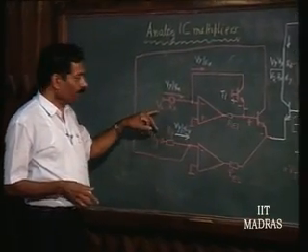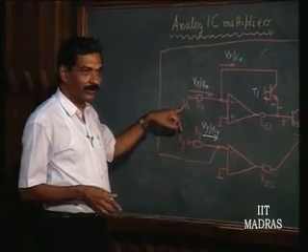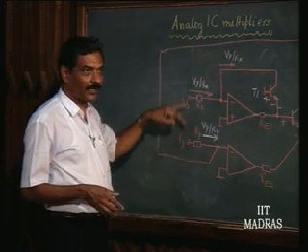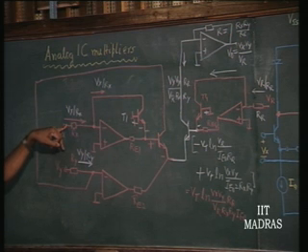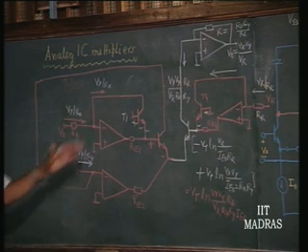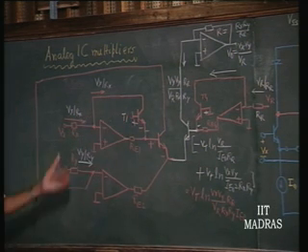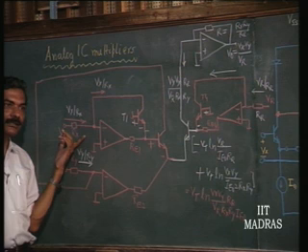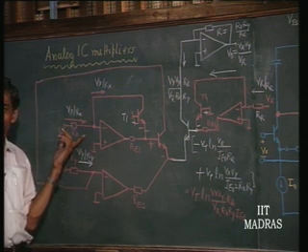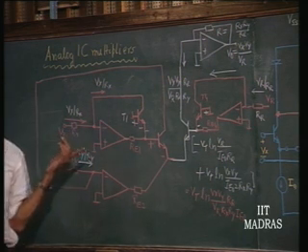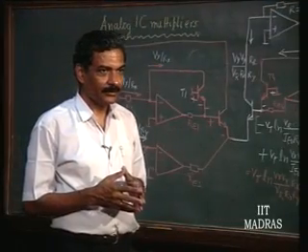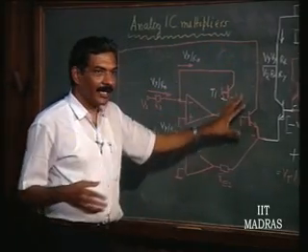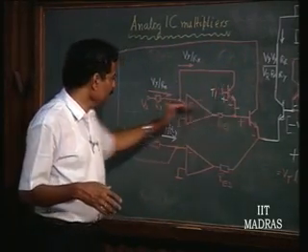for example, V_x has to go up to 10 volts, V_y has to go up to 10 volts, or V_x has to go up to 20 volts, let us say, because it is a single quadrant multiplier. We might like to go up to 20 volts, it is simple, and we want the operation of this to be limited to some 1 milliampere, then we automatically know the resistance as 20 kilo ohm. If it is 10 volts, we know the resistance has to be 10 kilo ohm. So we can limit the dynamic range of operation of this by limiting the current into this.